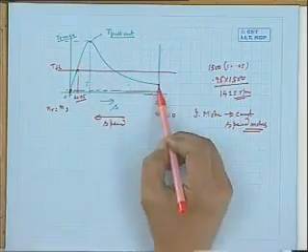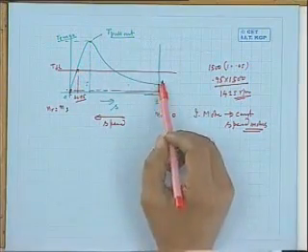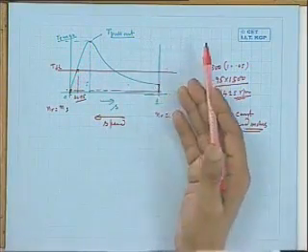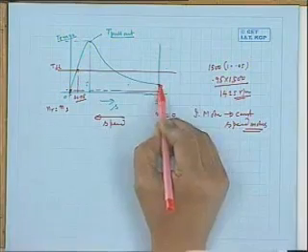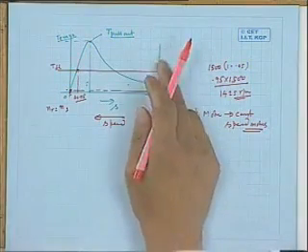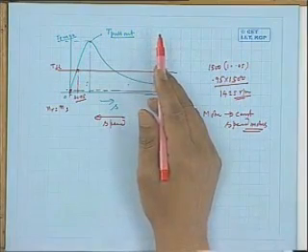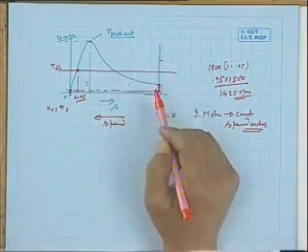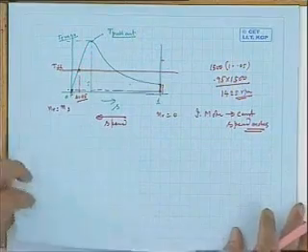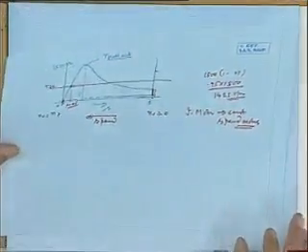Therefore, those aspects are to be seen. How to increase the starting torque of the machine, because the starting torque for a typical induction motor with full voltage supplied is this much only, and if it is less than the full load torque, the machine will fail to start. So somehow this torque is to be increased during starting, and it should be greater than this load torque, then only the machine can accelerate. Are you getting it? So those aspects we will discuss.